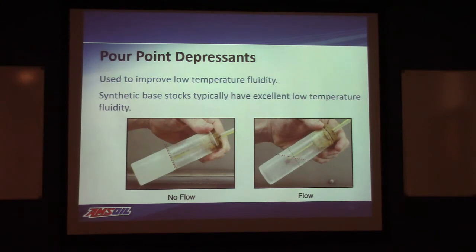Now, when you look at synthetics, they don't have paraffins in them, so wax crystallization isn't an issue. So synthetics have good, better low temperature usability, yet they don't need pour point depressants. Again, something else you don't have to put in there, you've got room for other stuff.